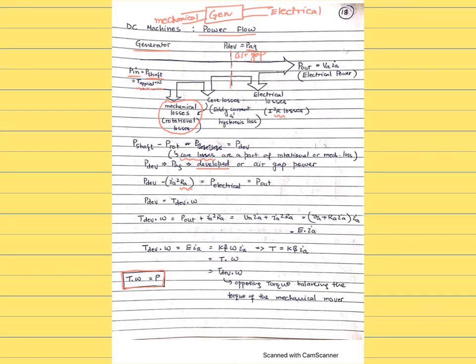So you actually take off, in case of shunt and series, the field winding loss, and most of the time in separately excited you don't consider it, so that's why it is not shown in there. So from the exam perspective, you will be told whether to ignore the field winding losses, or otherwise you can consider them as well. So from here it can also look like this, IF squared RF, let's say.